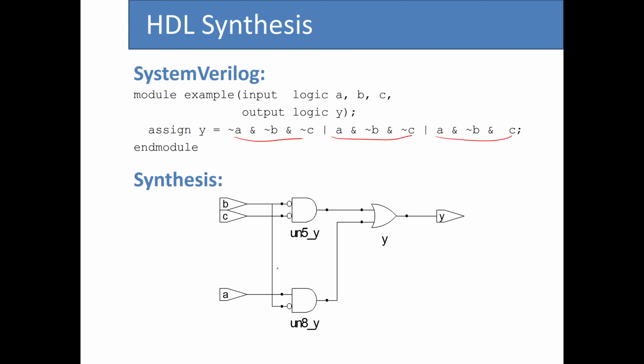But now the result of synthesis has two input AND gates and one 2 input OR gate. The reason for that is in the process of synthesis, we actually can do simplifications too, whether we want it or not, right? So depending if we require simplification or not, we can do that during the process of synthesis, and we get a simplified version of the function.